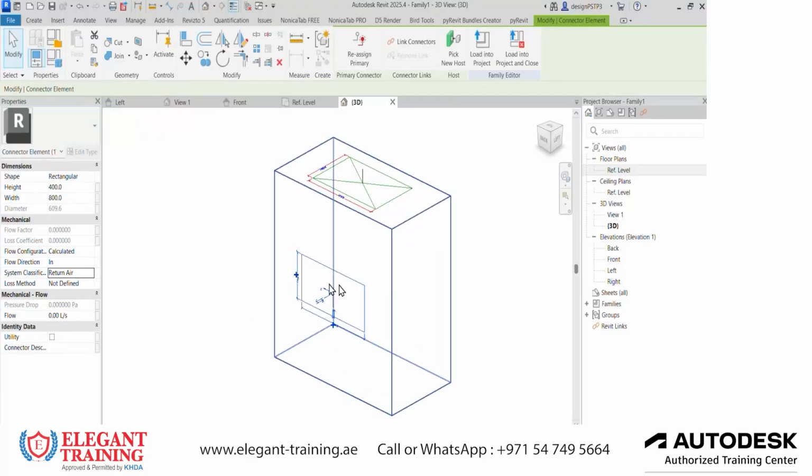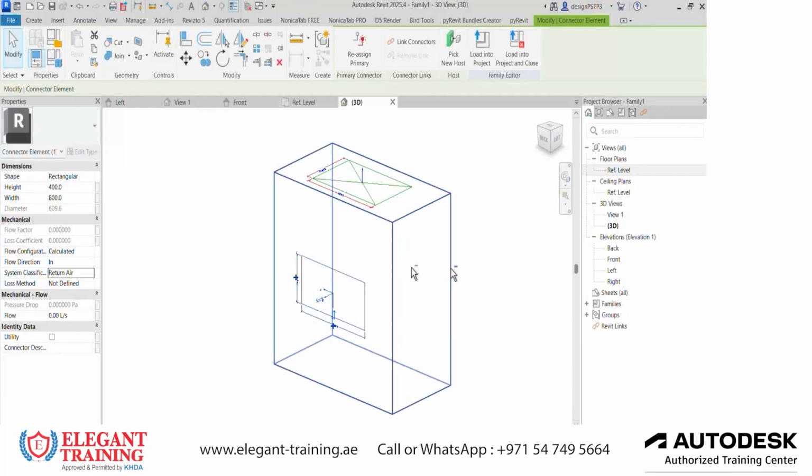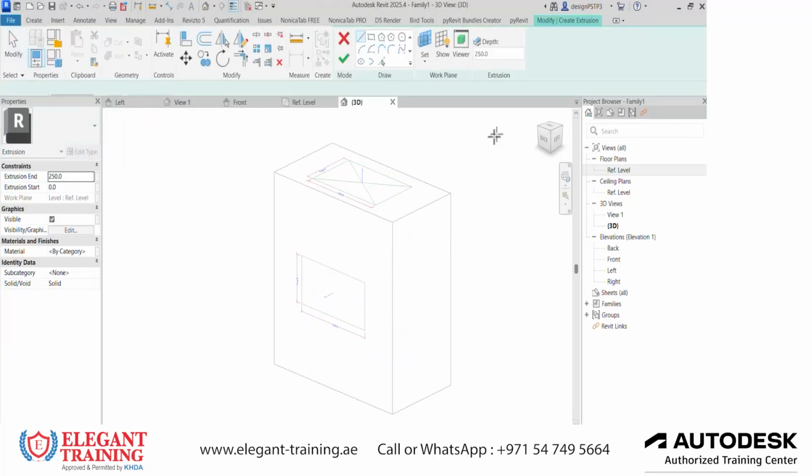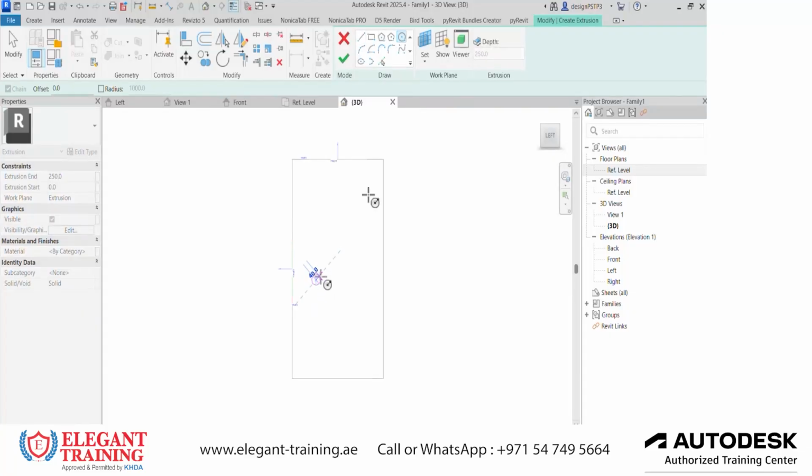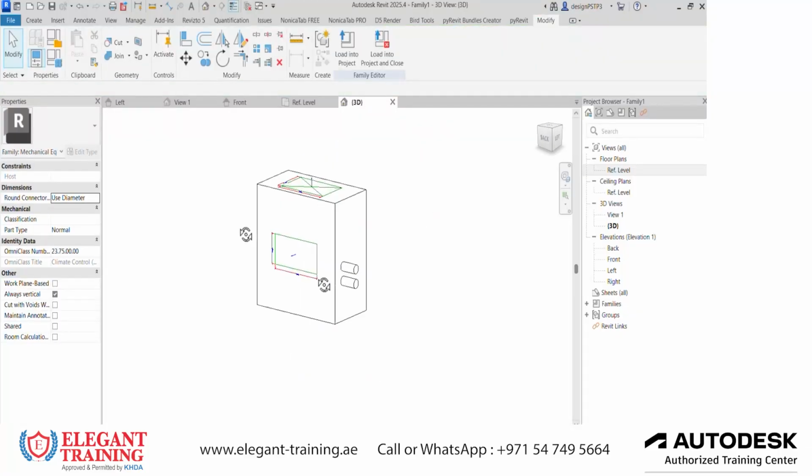For the piping, actually we need a face. So I go to Create, I choose extrusion, then I pick a plane. I pick this plane, so that I can sketch, because I need a starting area. Let's make it like 60. Let the pipe coming out be 60 by 60. Click finish. So this is an extrusion, correct?